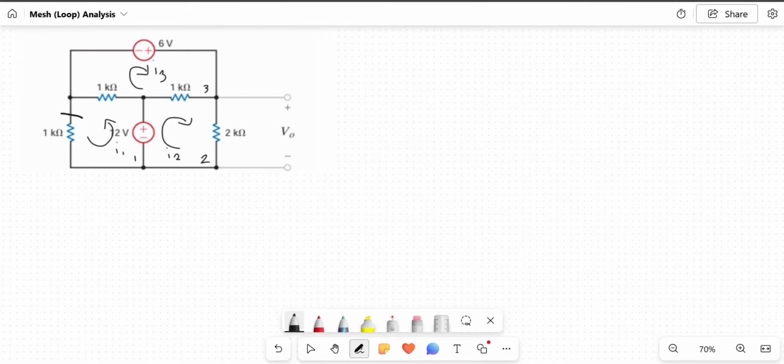And now I want to start off with this 1 kiloohm over here. This current will be going down over here, and there's no other currents interfering with it. So this will be written as 1 I1 plus, it goes this way and goes into the voltage from the negative 12 side, so that will be written as plus negative 12 volts, plus it goes this way I1 while I3 also goes this way.